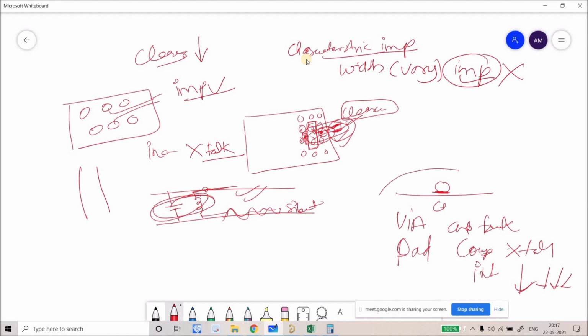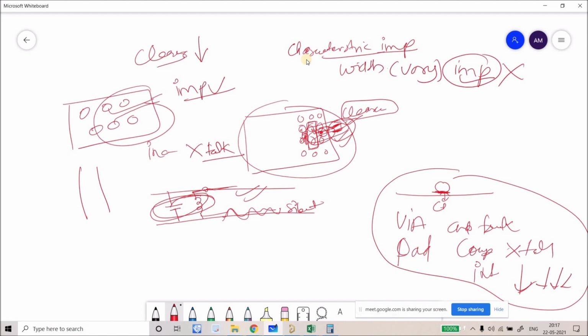So this is common sense, and that's why, because if we change the impedance profile, there will for sure be a problem, right? Because we are dealing with very high frequency tracks and we don't know which track will create issues. That's why the modeling or simulation of high speed layout is very important. But out of these two options, as a hardware designer, we know that here we don't have that much coupling, so we have to choose this option. We have to reduce the clearance rather than reducing the width of the track.